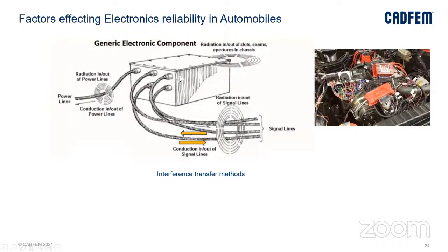And again, the signal lines that are coming out of this case can also act like an antenna and radiate. So these radiations can couple to nearby systems or nearby electronics present close to this system, and can also affect their performance. So we call this radiated emissions.